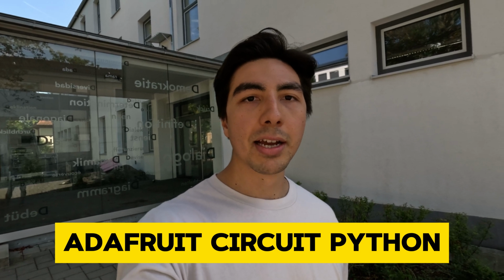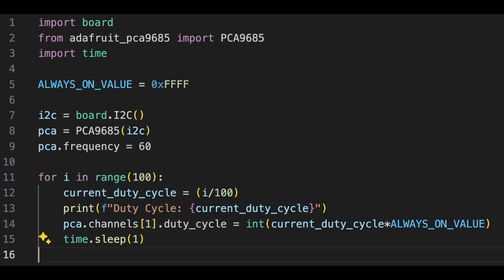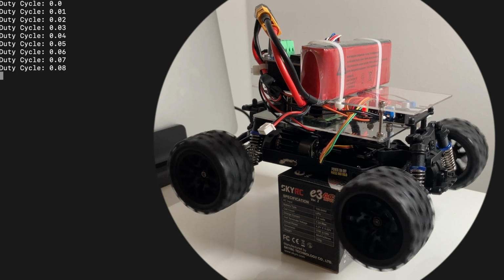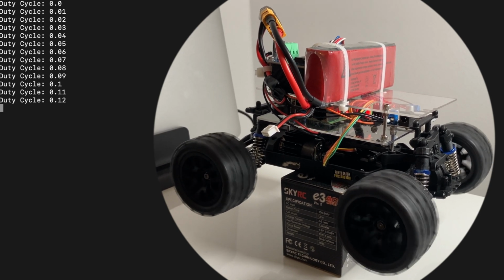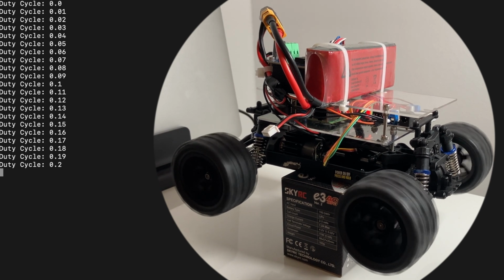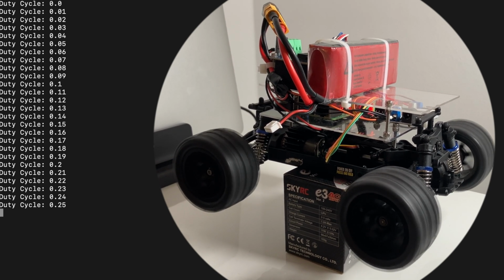And anyways, alright, so the next step for this video is going to be to control the motors, and for that we're going to be using the Adafruit CircuitPython library together with our servo driver board that we showed in the last video. And for that, we have this minimal script here that you can see on the screen. And I'm just going to gradually increase the PWM levels that's going to the motor driver. And you can see here that the RC car is gradually increasing its speed. We're going to be using the same board and the same library to be controlling the steering of the car by moving the servo motors.